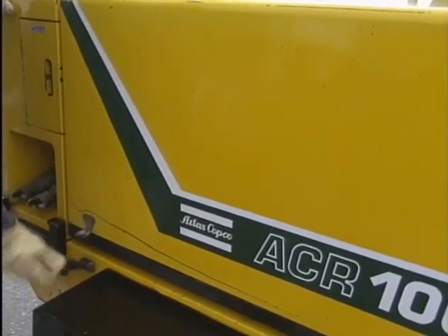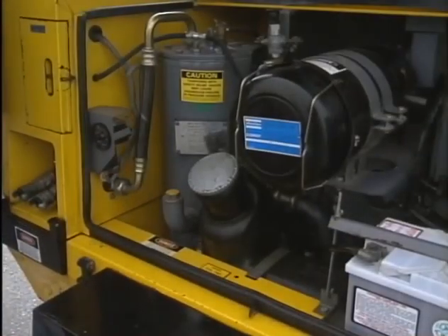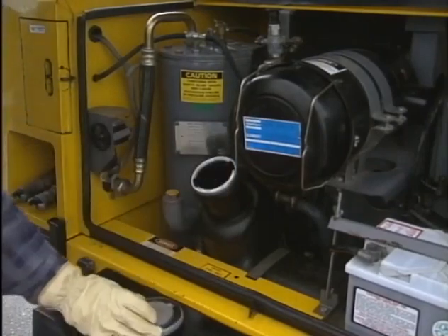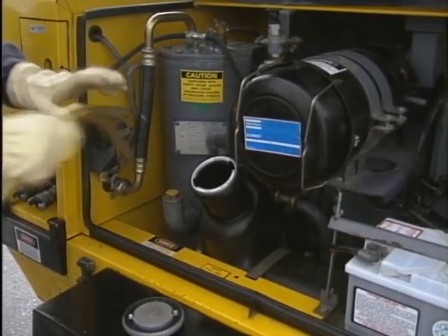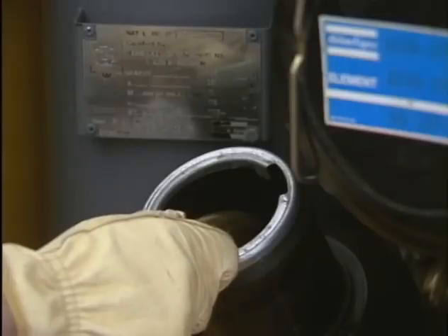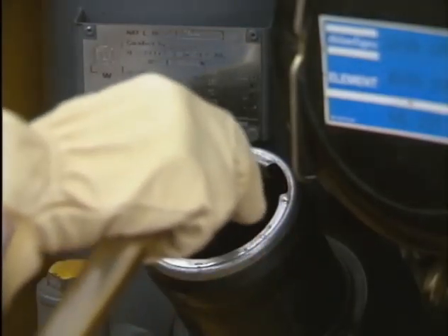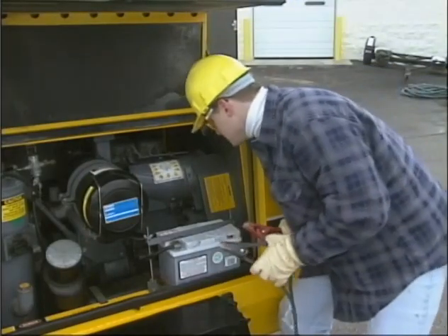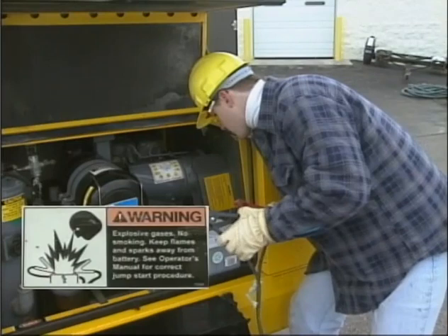Fire prevention. Avoid fire hazards. Always stop the engine and allow the air compressor to cool before you refuel. Do not refuel while smoking or when near open flame or sparks. Never overfill fuel tanks or fluid reservoirs. Batteries produce explosive gases. Keep open flame or sparks away. See the manufacturer's instructions when servicing the battery, when using jumper cables, or when using a battery charger.